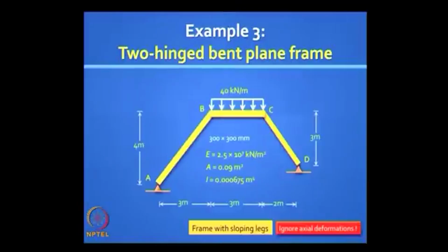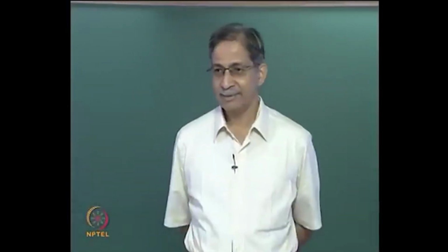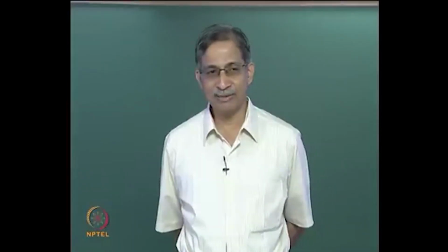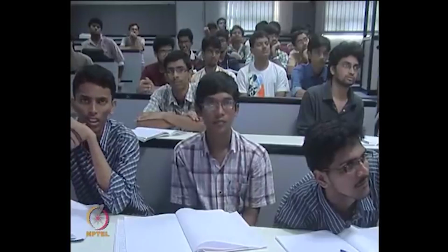What is the degree of indeterminacy, kinematic indeterminacy? Degree of kinematic indeterminacy refers to the active global coordinates. The absolute minimum when you don't have axial deformations. At the supports A and D, do you need to have anything? No. We don't even bother about finding reactions. We do the minimum work.